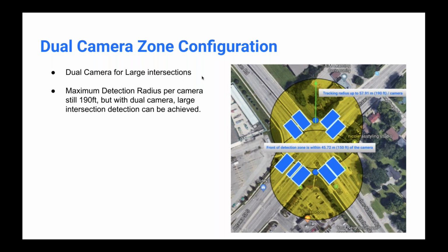For large intersections, you go ahead and install one camera, typically in the Northeast and one in the Southwest, or whatever's going to be the optimal placement to avoid occlusion and still see all four approaches. You can see the camera in the north here has a great field of view of the north and east, and the south camera can do the south and west.